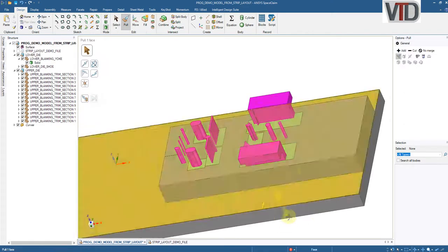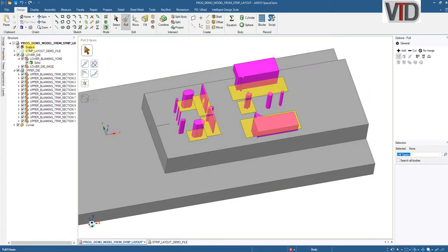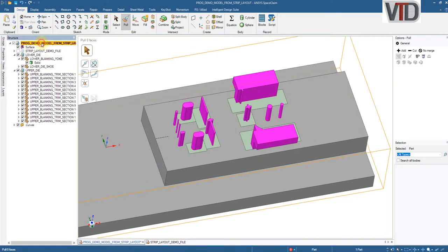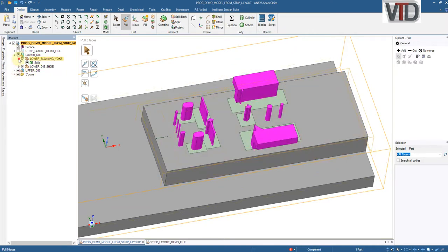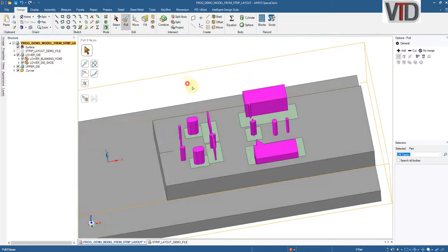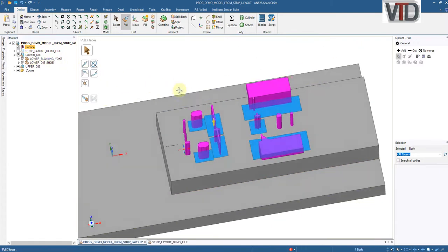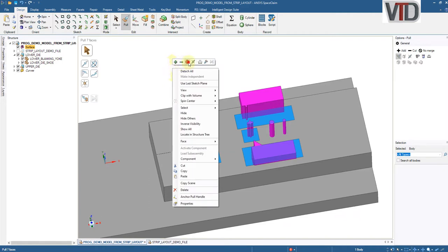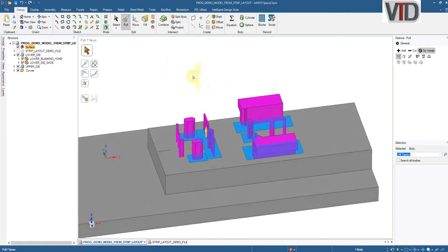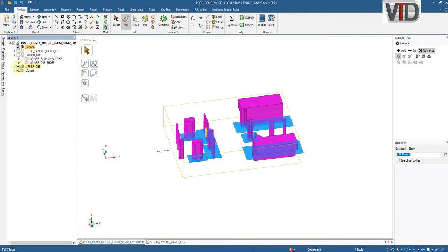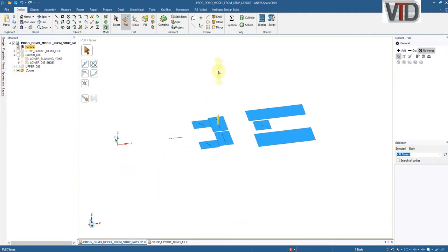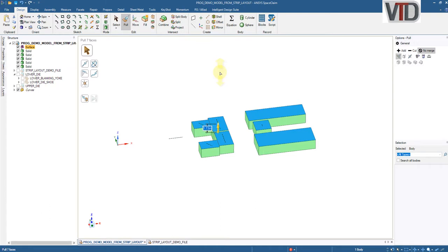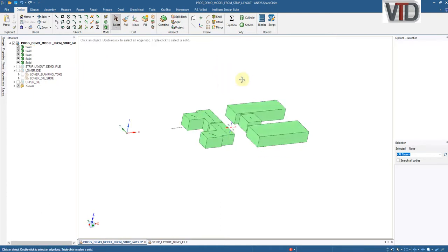So now I'm going to move back to 3D mode. And as you can see, I've got a surface here. So I'm modeling everything with the top level assembly active. And as I'm creating geometry, I'm dumping it into the sub assemblies. So I'm going to do the same exact thing in this case here. So I've got this surface here, and I'm going to pull this, and I'm going to do no merge, and I'm going to turn off this other data here, and I'm going to pull this down, say 2 inches. Okay.